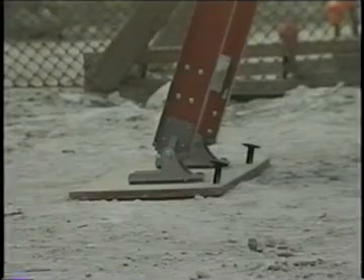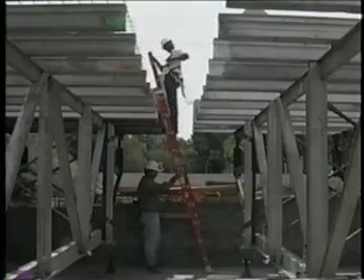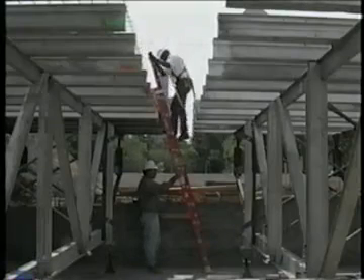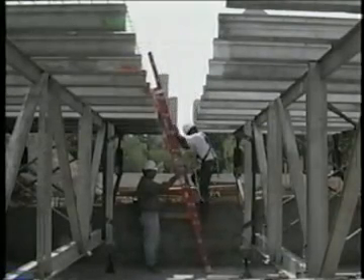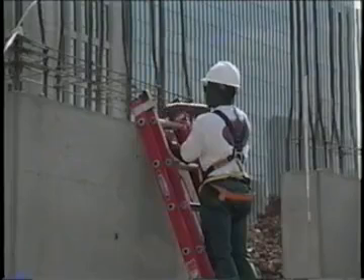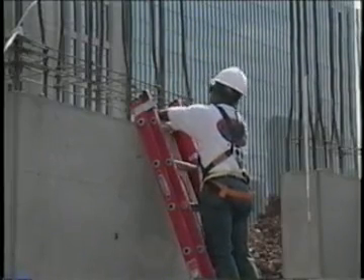Block the base of the ladder if the ladder does not have safety feet or if the surface is very smooth and the base could slip. Someone should hold the ladder at its base while a worker is climbing up or down an unsecured ladder. Face the ladder and do not carry anything in your hands while climbing. Only one person at a time is allowed on this type of ladder. Straight ladders should be tied to a good anchorage point at the top of the ladder whenever possible.